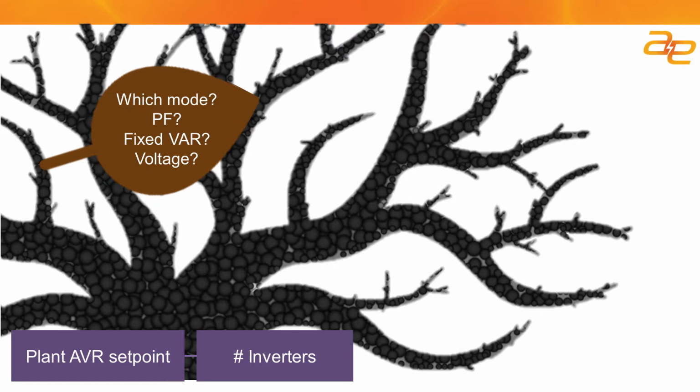The inverters generally are running in reactive priority mode, so if you command 10 kVARs from each inverter, you're going to have some line losses through the site, but basically you're going to get out from the site the same amount of VARs all the time, regardless of what the variable irradiance is.